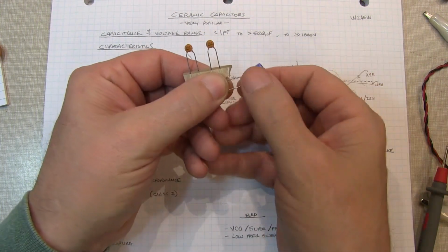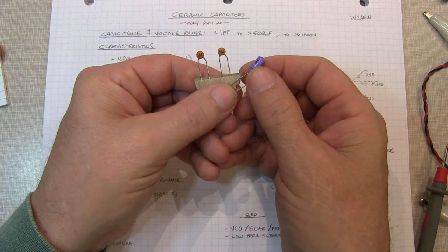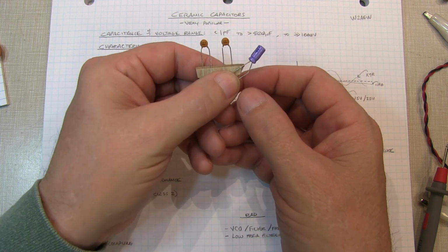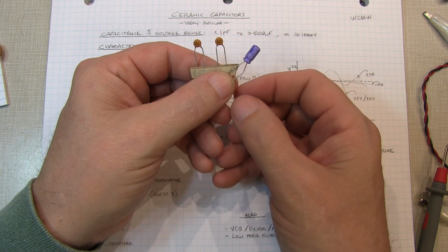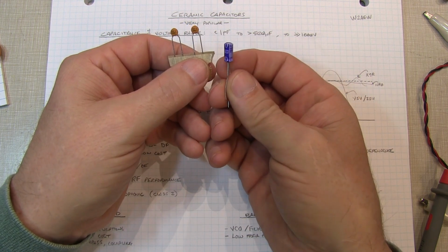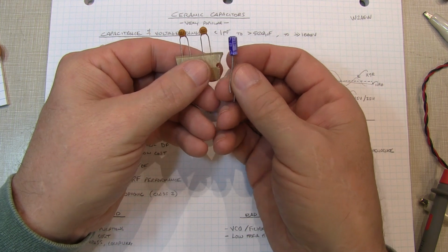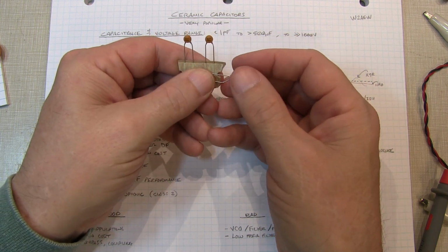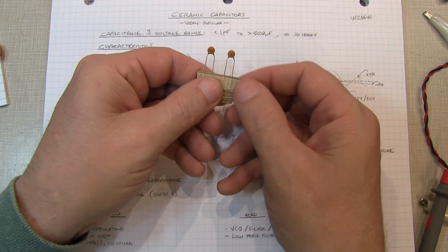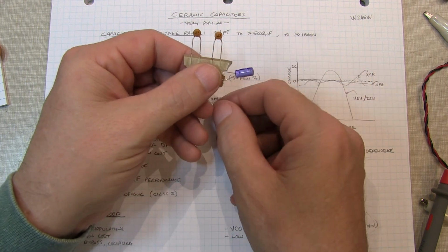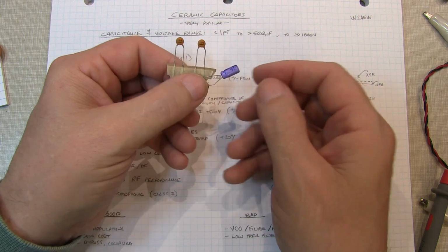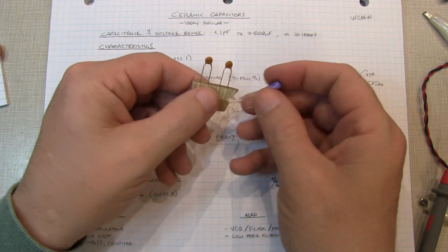Now, something I'll mention at this point is if you're reviewing a schematic or you see something online you're going to go build and the capacitors aren't labeled in terms of what types they are, whether they're ceramics or electrolytics or film or mica or whatever, the most likely case is that any of the polarized caps are electrolytic caps, and in many cases could be substituted with tantalums. Any of the others that are non-polarized, generally lower value caps, they're most likely ceramic capacitors. If the application really warranted something other than those two, hopefully the schematic would be labeled that way. But it's a pretty safe assumption that the polarized caps will be electrolytics, and the non-polarized ones ceramic.